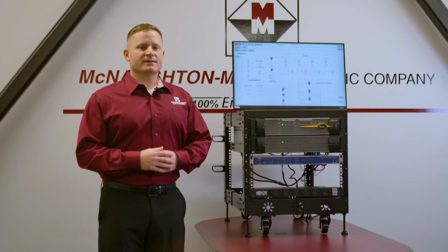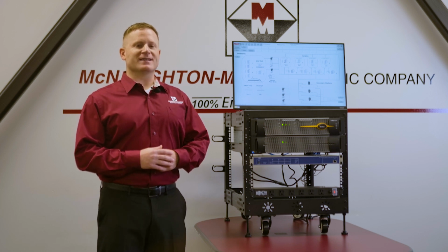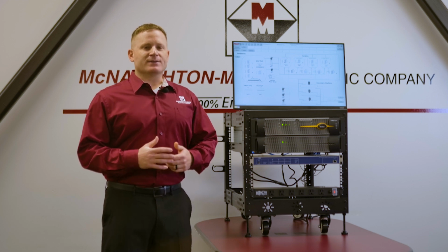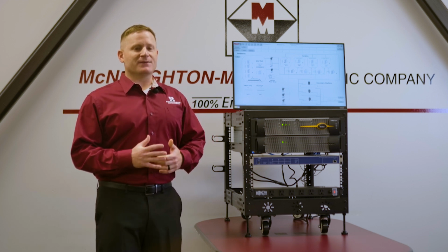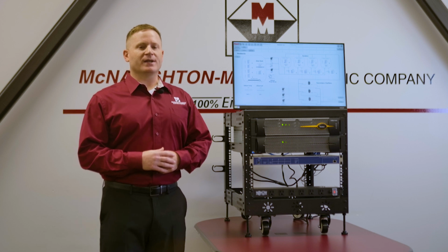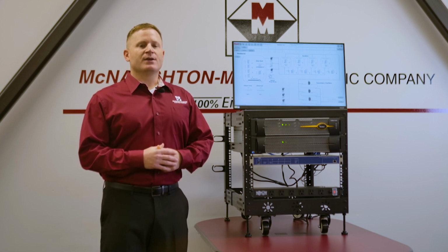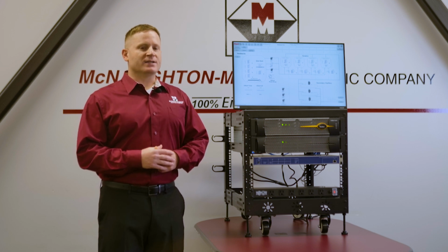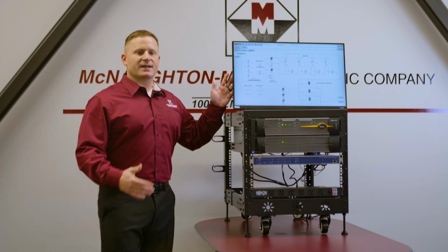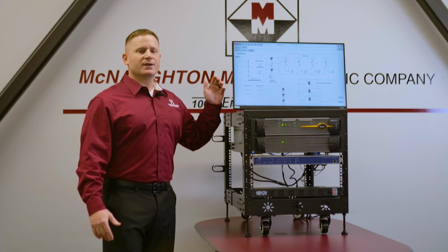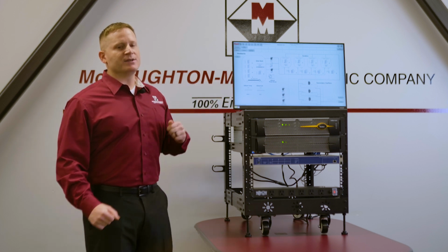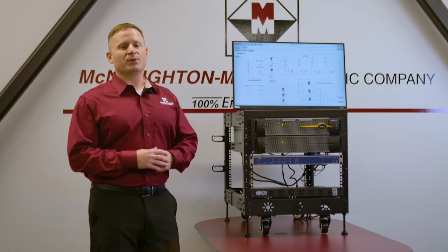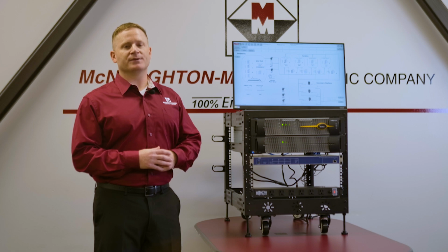For applications, it appears that the ftServer has a single system image, making it simple to operate and maintain. This also allows single licensing as if a single system for both operating systems and applications. Your applications run without modification or failover scripts. Displayed on the monitor is a PlantPAX HMI application running on the Stratus server. Notice this application will continue to run normally without interruption when I simulate a CRU failure by pulling the power cable out of the bottom CRU.